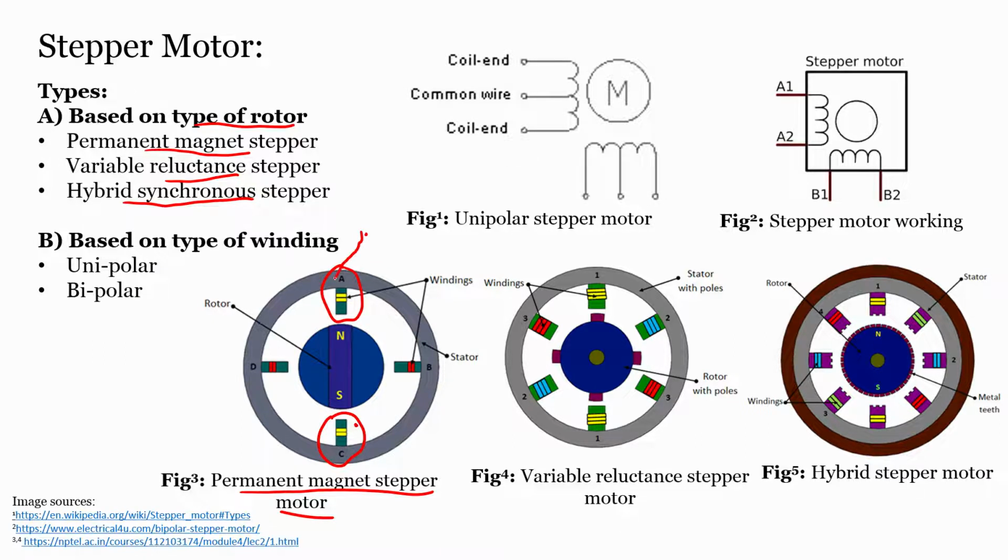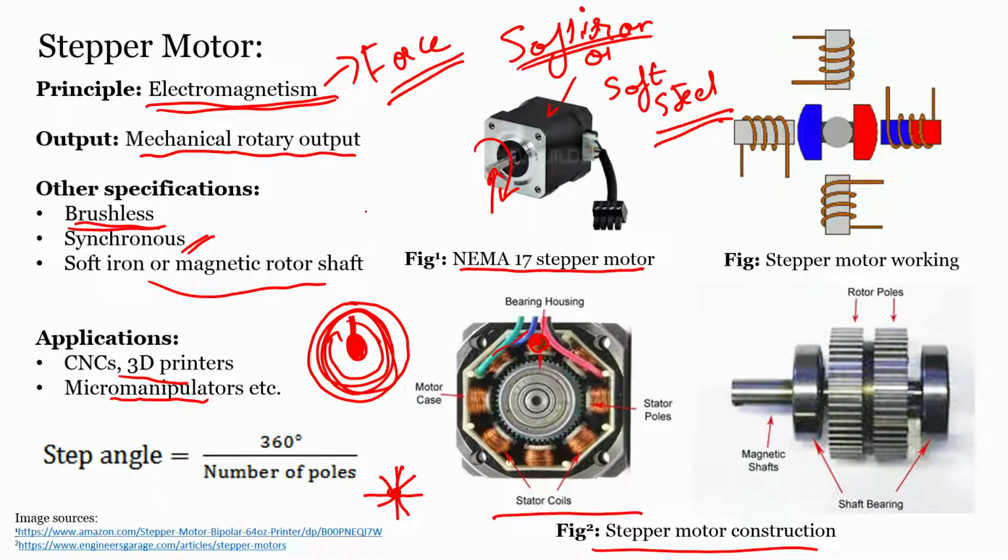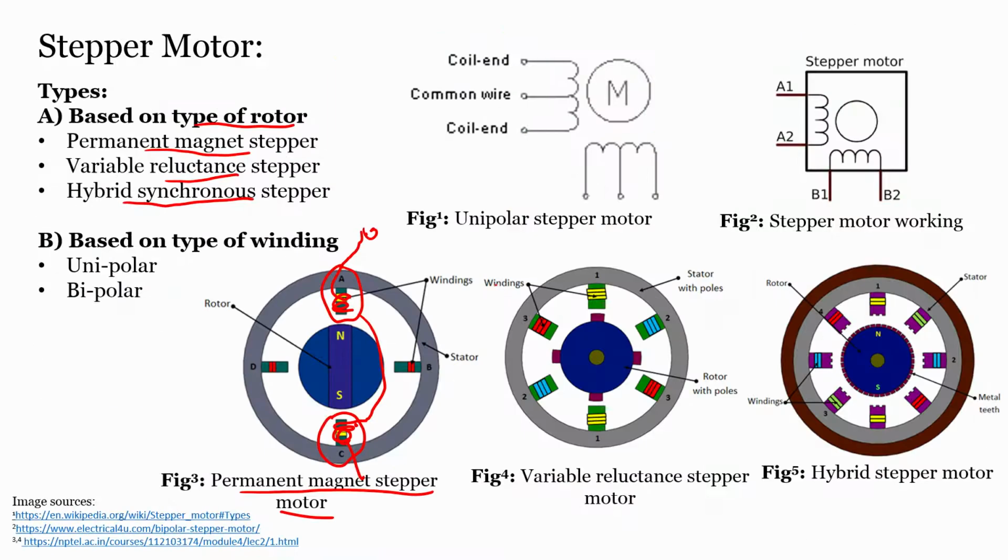So it's like the cable comes, there were 4 wires, right? It will be like the cable comes, it will rotate about this stator pole, it goes here, it will rotate about this and go out. So what happens is, one coil, say the green one that we saw in the previous slide. The green and blue are close and red and black are close, I am just telling you an example. So the green wire over here will come here, rotate around the pole, go to the other pole, rotate around it, and will go out as, say, the blue wire.